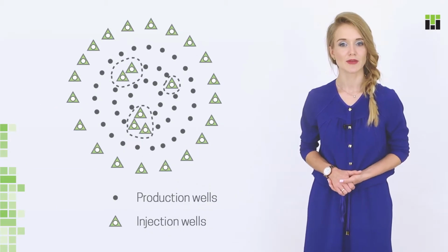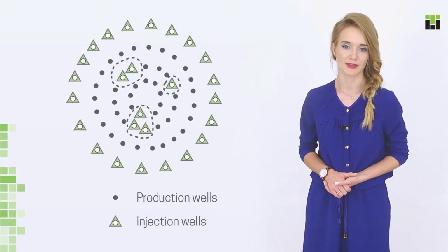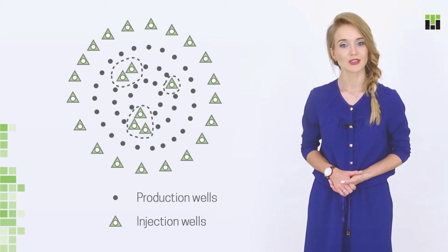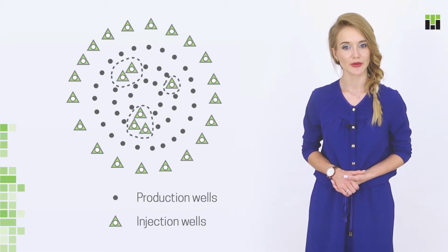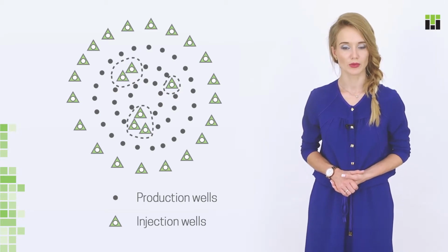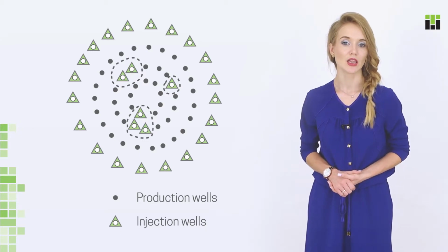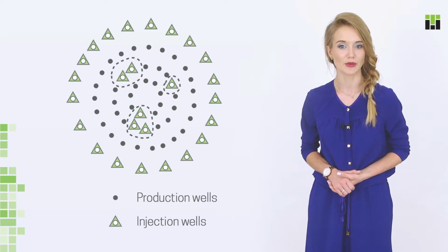As this system evolved, more water flooding designs appeared, such as selective water flooding. Its main idea is to place injection wells not according to some regular pattern, but in certain field areas, depending on geology and geometry of the oil pool. It is often combined with other water flooding systems, as it allows for focused extraction of oil from unswept areas.